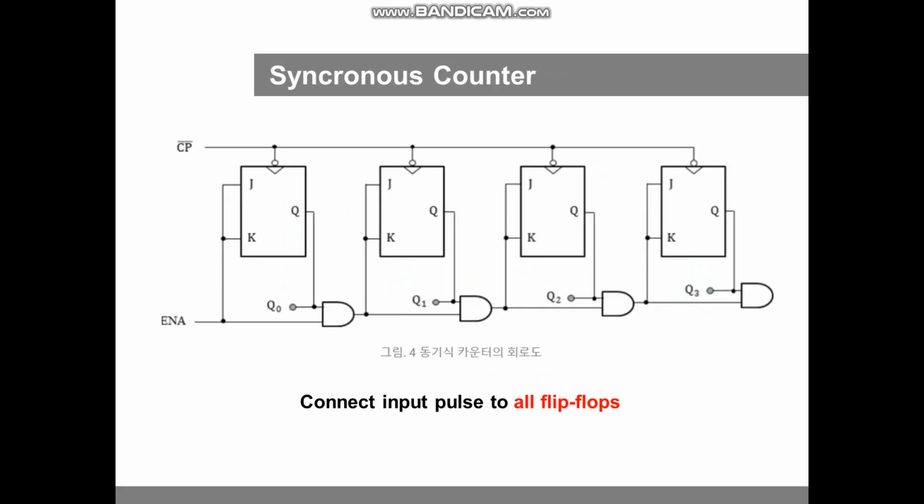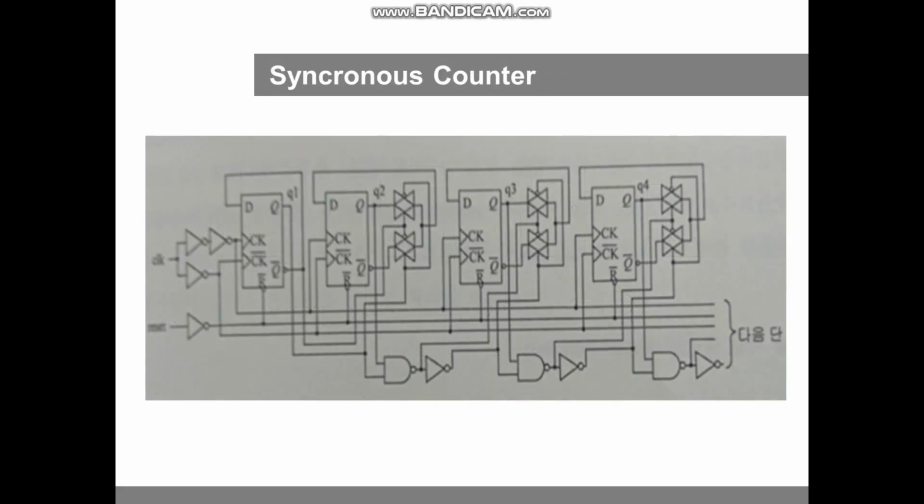And synchronous counters have the advantage that pulses are applied simultaneously to all flip-flop inputs and the outputs change synchronously. Synchronous counters use D flip-flops in the design.